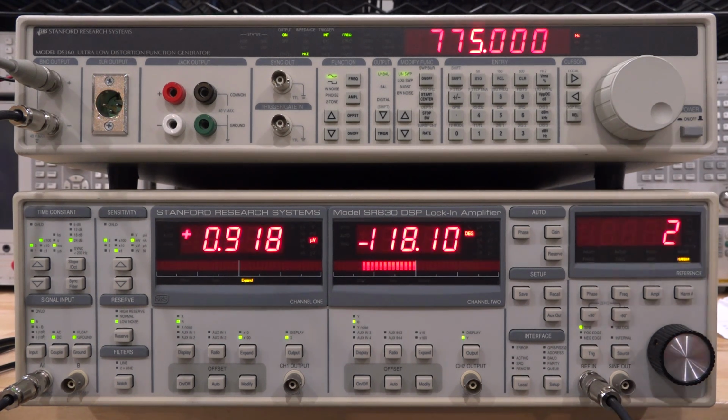If I go to the third harmonic, you will now measure the third harmonic power. You can see that the third harmonic power is significantly lower, 0.1 microvolt. Go to the fourth harmonic. There you go. Here's the fourth harmonic. It's a little bit larger, 0.29, 0.28 microvolt. And then the fifth harmonic. We shouldn't really worry too much more beyond that. You can see it's already dropping, 0.1, 0.2.